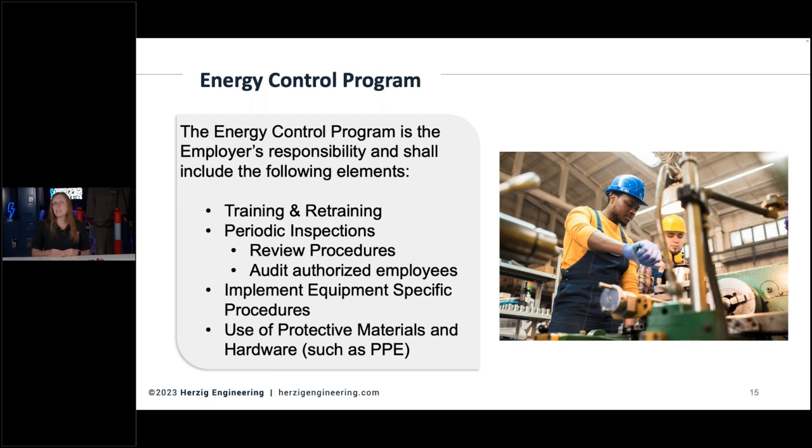I see that quite often. They think, well, of course you're going to dissipate this. Okay, but what do they say about the word assume? Makes us all look silly, so don't do that. We write it out. It's a specific procedure. And also keep in mind that there could be protective equipment or other materials needed in order to implement that lockout tagout procedure, so make sure those are available for the worker at the time.